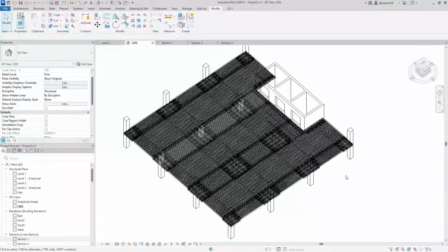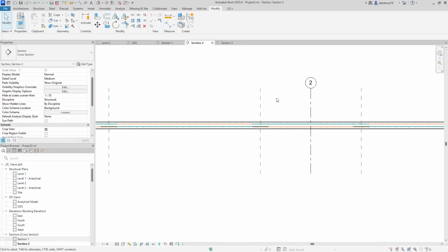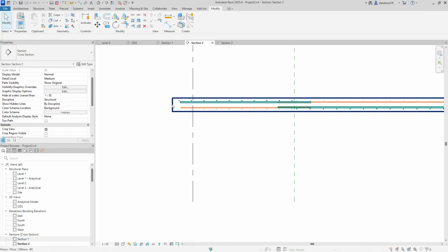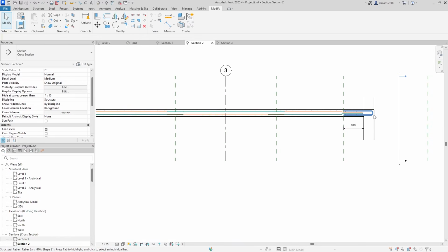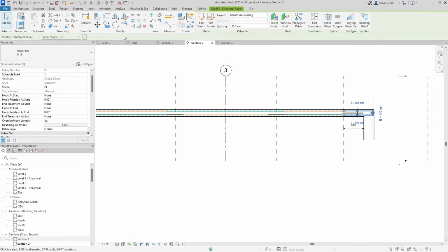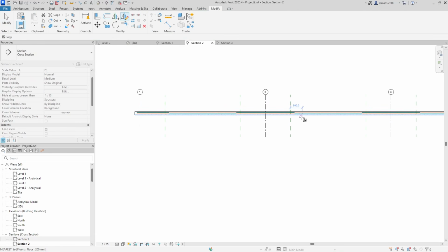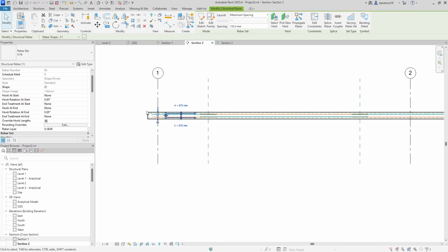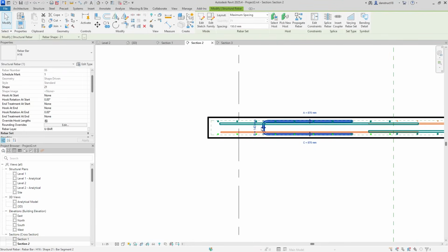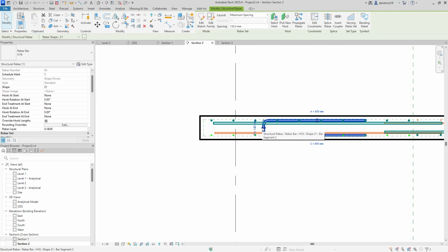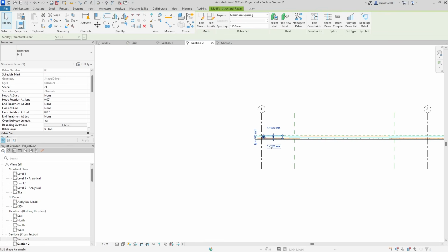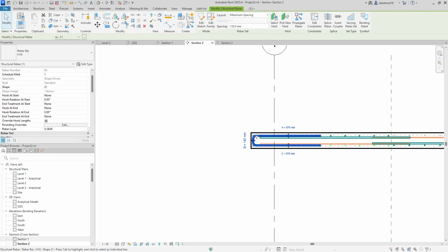Now let's go ahead and model the U bars on all the other ends. So in this case here, I'm going to switch here back to section 2. And over in section 2, we see we don't have a U bar here. So I'll just go ahead and select this one like this. And I'll just click on mirror draw axis. And I'll just specify any points. Actually, don't need to be too specific. Then click here. And I can just go ahead and drag it however I want. So I'll just use my arrow key to nudge it to the edge. There we go. All right, good.